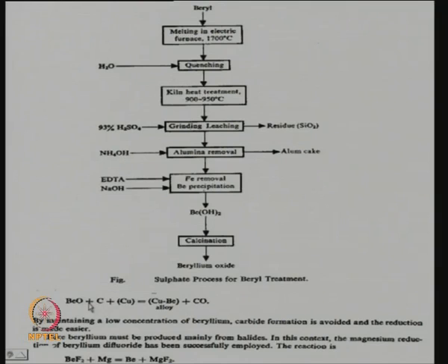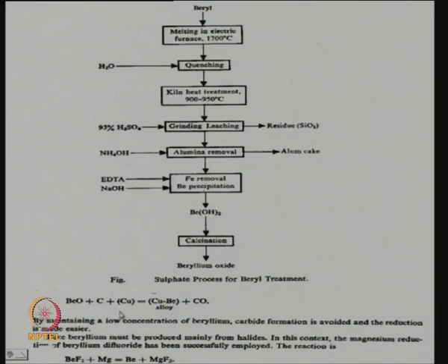There is another advantage. In the industry, copper beryllium alloys are needed. Actually, a lot of beryllium is used as copper beryllium, as springs. Copper beryllium alloys make beautiful springs, which retain their springiness. So, it is a double advantage. You are getting a product you want, and at the same time the product makes it easy for the process to occur. So, beryllium oxide is reduced by carbon in the presence of copper. We produce copper beryllium alloy and CO.